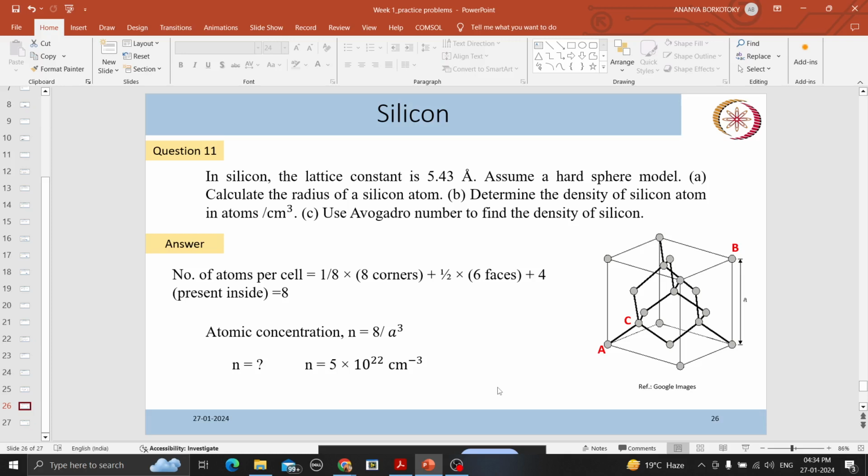In the order of 10 to the power 20 per centimeter cube. Okay, 10 to the power 20, that will be highly doped, right? Yeah, definitely. Almost 1% impurity will be there. Yes, so 10 to the power 16 or 17, those are typical values in centimeter cube. Again, the unit is important.